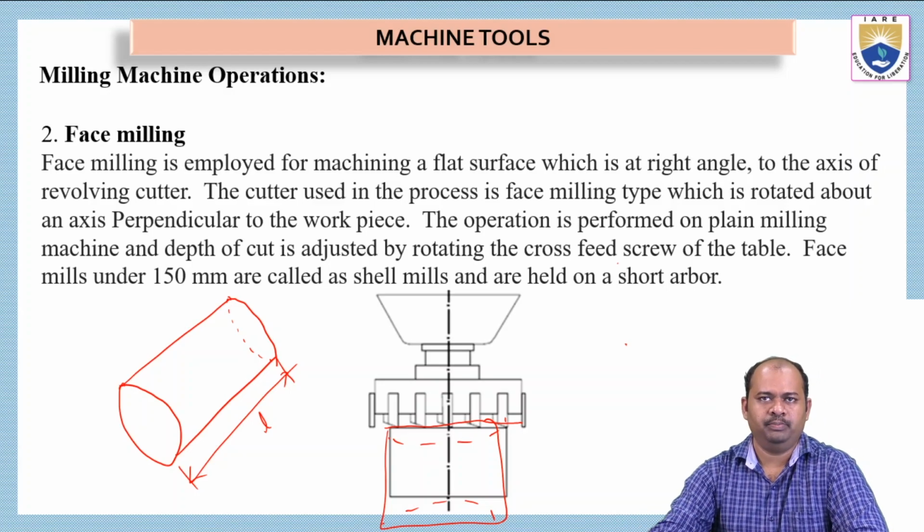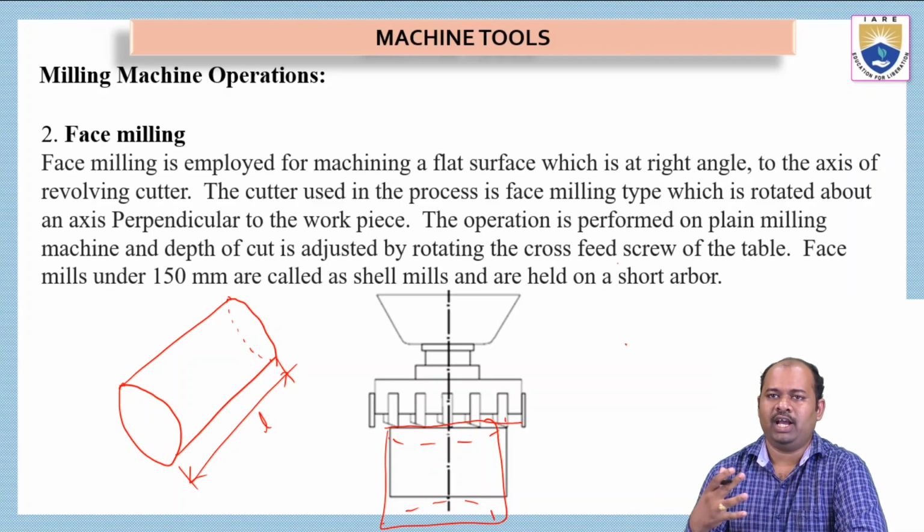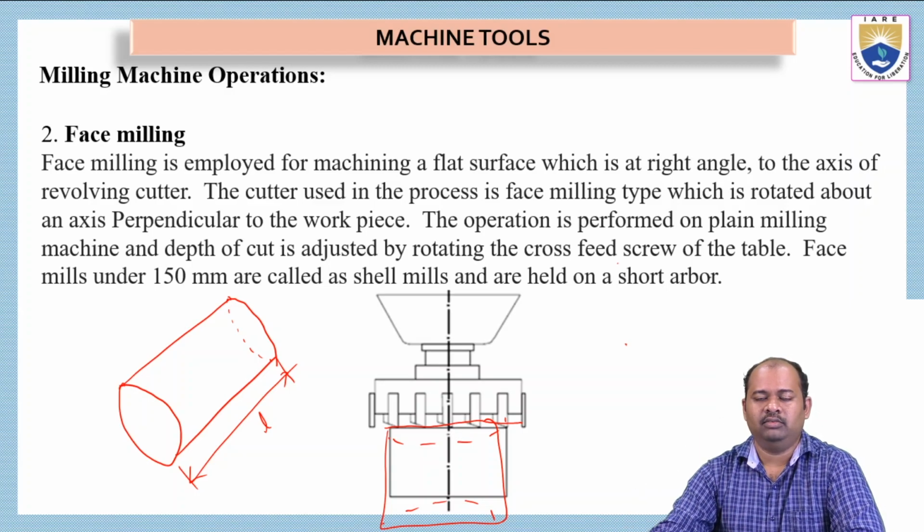Okay, so face milling is employed for machining flat surfaces which are at right angle. So for getting the flat surfaces, we have to use this face milling, which is perpendicular to the rotation of the tool. Okay, rotation of the revolving cutter.